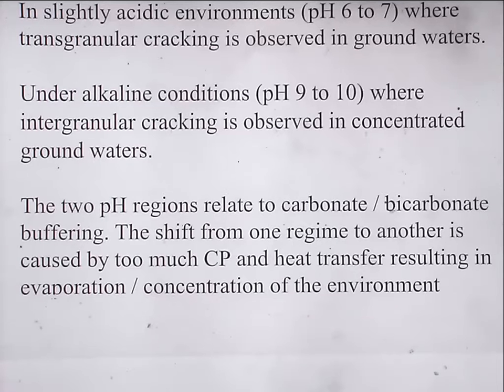Then we also produce some acidity when the oxide forms. It's called hydrolysis of the ions. So the composition of the solution inside the crack is low oxygen, higher acidity, and there will be some other differences between the bulk solution and the interior solution. And that all contributes to changing the potential down here, despite the fact that the bulk potential appears good on the outside of the surface of the bulk component.